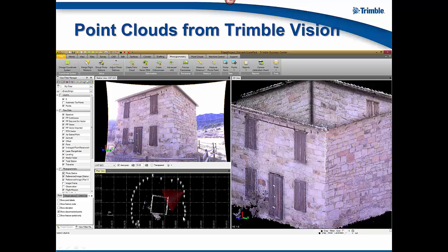So what we recommend is that the ratio of the distance from a station to an object to the distance between two consecutive stations is not more than 4:1. That means if you have 100 meters between the object here and the station, then the spacing between two consecutive stations should be at most 25 meters.